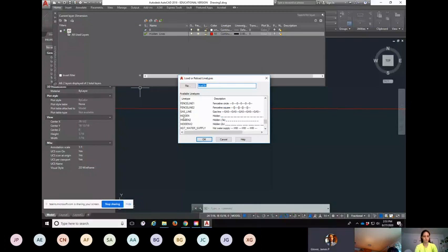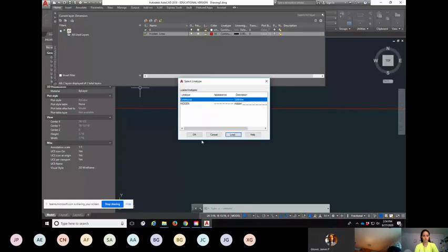Hidden is what we usually use for most of our drawing. If the separation in our line doesn't show up well in our drawings, then we can change to hidden line 2 or hidden times 2. So we'll change that.